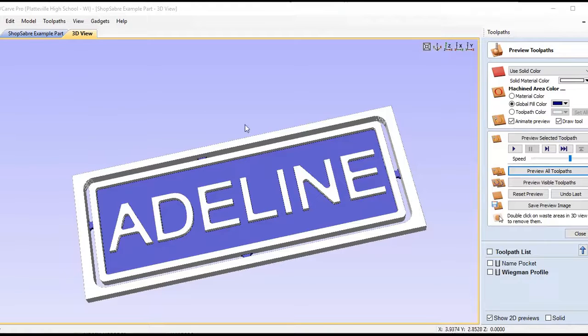Okay. So as we go through this, we wrap up by cutting our profile tool path out, and you can see the preview of that right here. I've got tabs positioned on the straightaways. I don't like having tabs positioned on corners. I like having our tabs positioned on a straightaway, part of our block. Just makes for cleaning that up a lot easier.